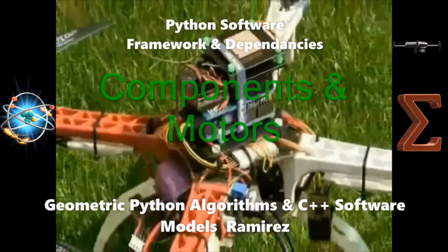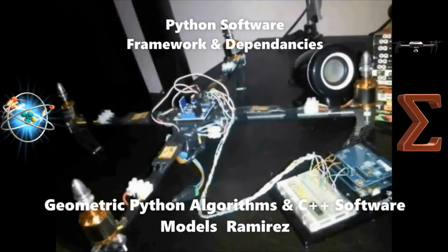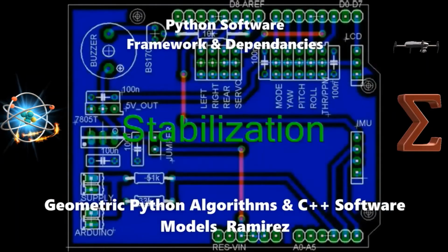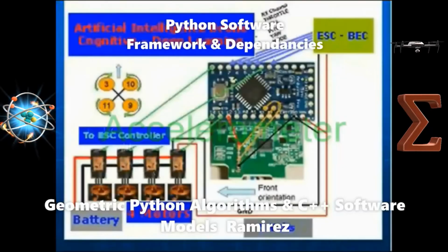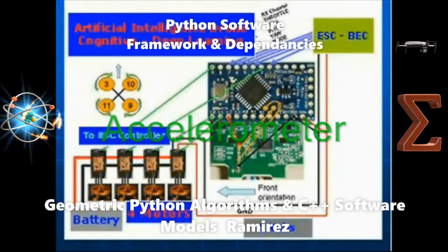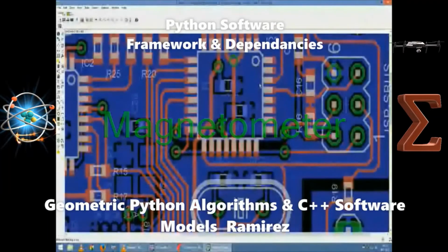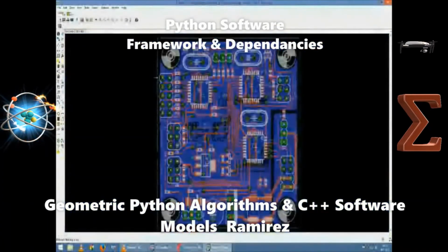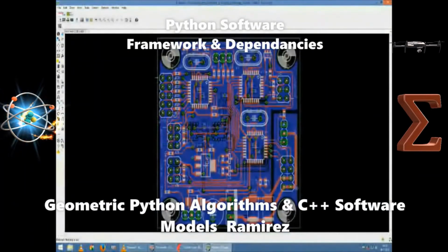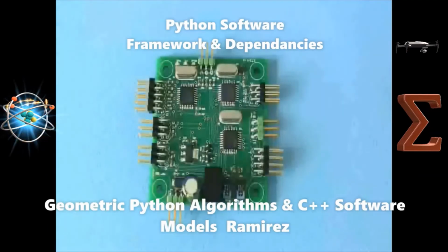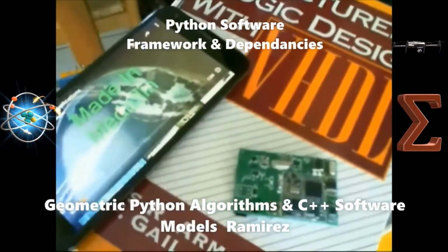Artificial intelligence drone. For stabilization and orientation, it utilizes a 3-axis gyroscope and 3-axis accelerometer. For navigation, it has a magnetometer and a GPS antenna. The system also includes an onboard SD card for data logging. All of this is integrated in a small form factor. I also integrated a telemetry radio and airspeed sensor system.